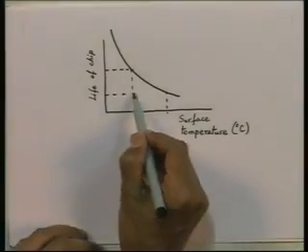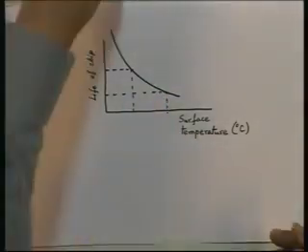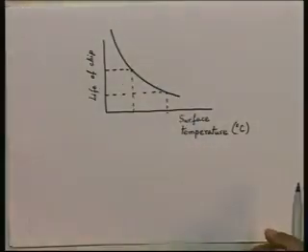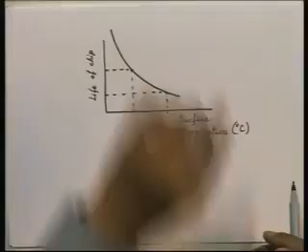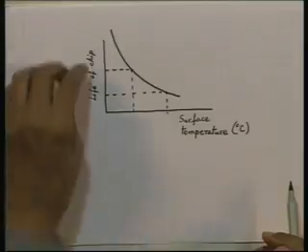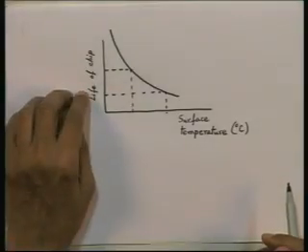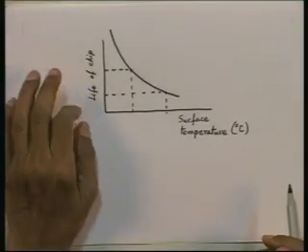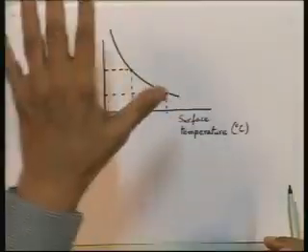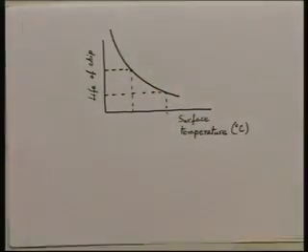So, going from 52 to 97, if the temperature stays at 97 for long enough, I might reduce the life of the chip to a value below what is desirable for continuous safe operation. In fact, typical surface temperatures that we need for chips are in the range of 50 to 60 degrees centigrade. We do not like temperatures of 70 or much higher.